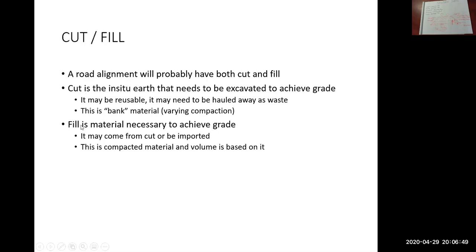So that's cut. Fill is material necessary, again, to achieve grade. So you're filling up to the subgrade level or bottom of subbase. That's the same spot. It could come from cut, or it can be imported material. Again, subgrade fill can be existing excavated material. It could be imported gravel. Again, this fill is compacted.